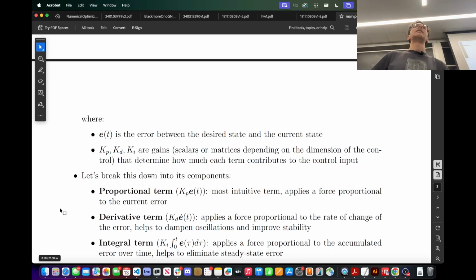However, as I'm sure someone who's used a PID controller before knows, did you use the integral term? No. Almost everyone is shaking their heads no. Why? Someone give me one example of why. Yeah, so if your error builds up very quickly, and your integral term is quite high, this can lead to introducing instability and phase lag in the system. And this is not good.